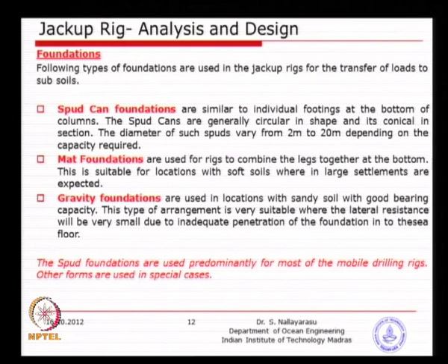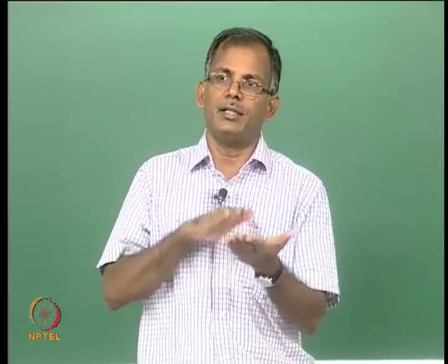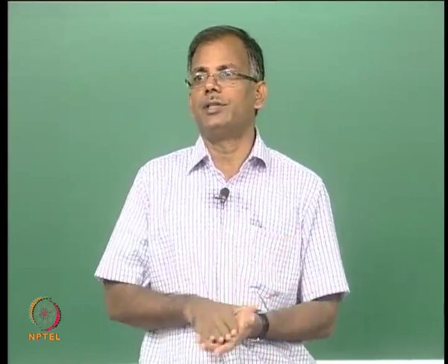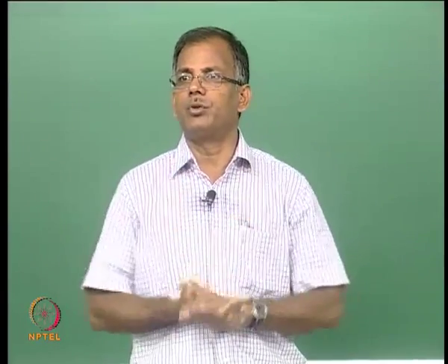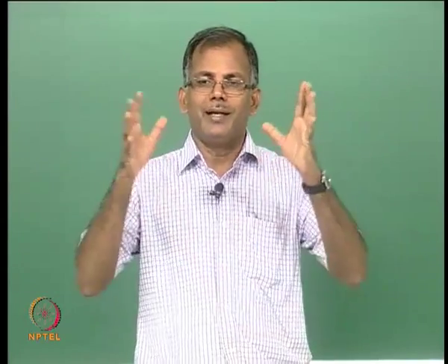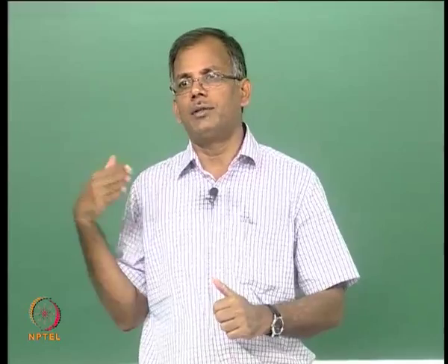Gravity foundations are normally not very good if you have clay type of soil, because gravity type of foundation relies highly on the weight of the structure. You make it heavier and the stability is achieved, basically the horizontal stability against sliding and rotational stability against overturning. So, you make it heavier and heavier, what happens? The structure cannot be moved even if you apply larger horizontal loads due to wave, current and wind.